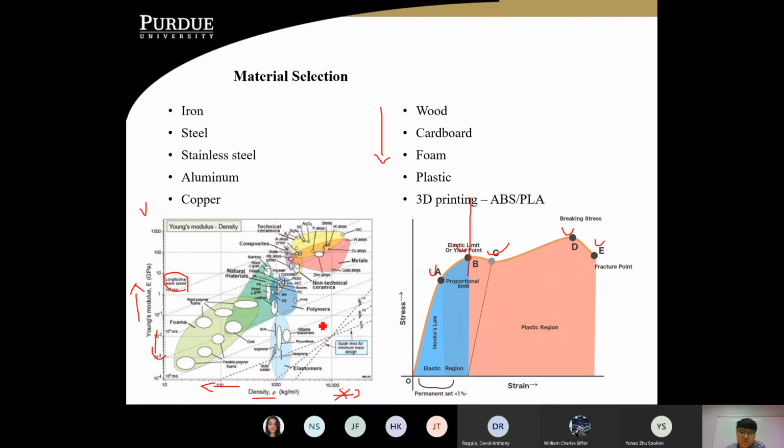Whatever material you choose, when you do a tensile test, whatever test you do, you'll always get a curve like this. It goes up and then starts tapering or whatever happens. There's always a yield point that's going to show up. Now the yield point, what I really want you guys to take away, is that the yield point determines whether the material can recover or not. So what I'm trying to say is that you don't want to get over this point, the yield point. Whenever the material starts passing this point, basically the material has plastically deformed forever.